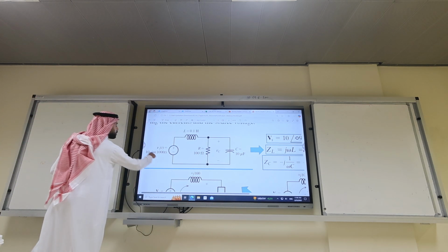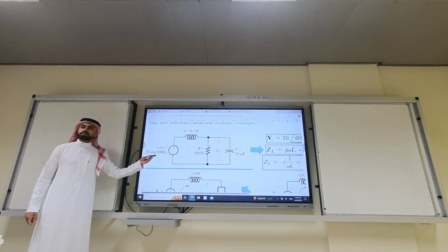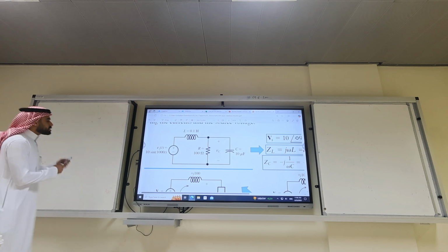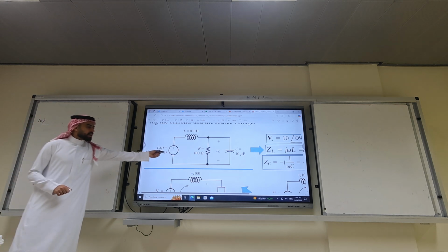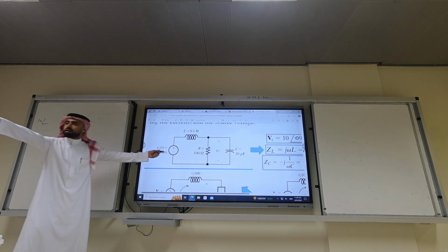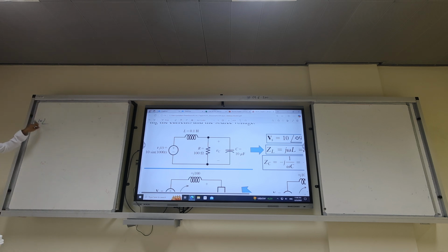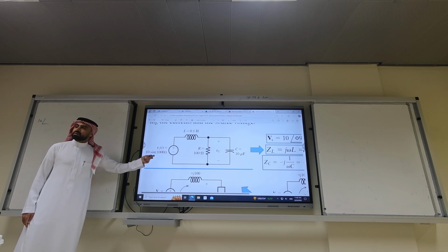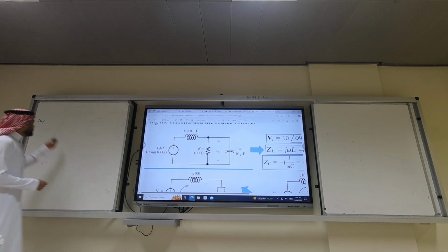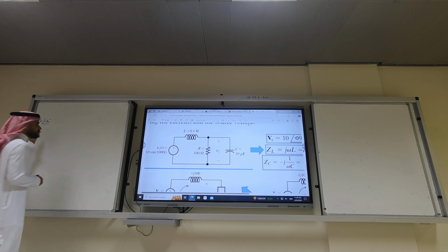Now here is an important point. What's the voltage source phasor? It's sine, so we need to convert it to cosine. So it has to be what? 10 angle 0? The sine is at angle 0. So convert it. Cosine. What is the phasor? 10 angle 0? That is wrong. This is sine, so to convert it to cosine 1000 t, it's minus 90. So this will be 10 angle minus 90. Get it? That's the voltage source.